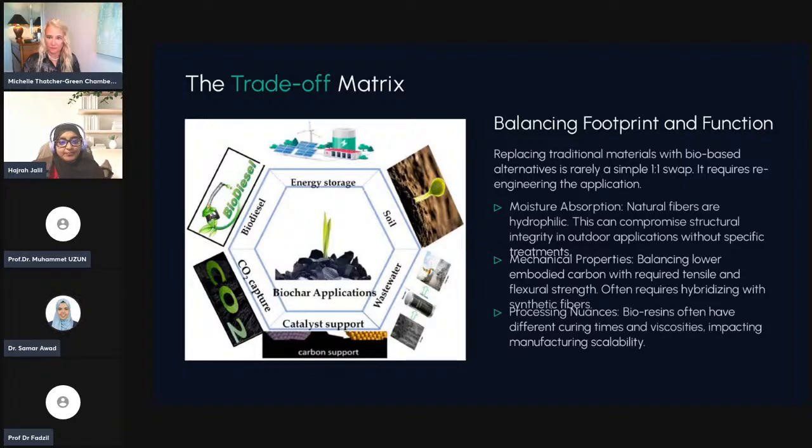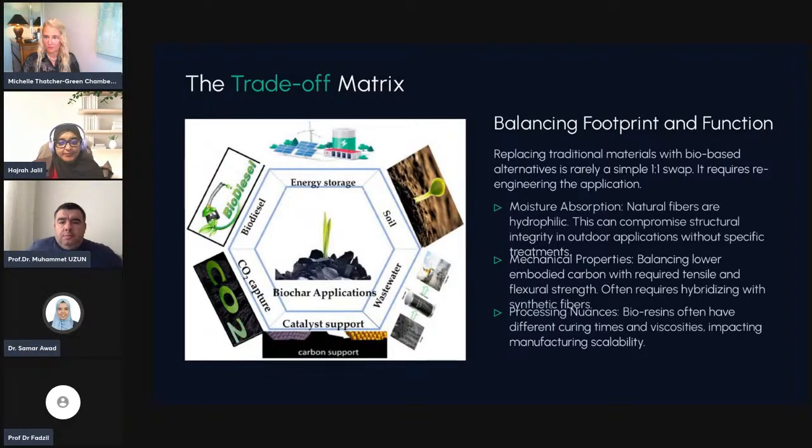Natural fibers are tricky. When we replace standard materials with natural materials, this process is tricky because natural fibers can absorb too much water or lack structural strength, meaning we must carefully mix and redesign them to function properly in the real world. So when we use natural fibers, we can make sure how they absorb water and measure the strength of these materials when we use them in a structure or as an envelope of a building. And I will present an experiment that will be published in an upcoming paper that I am testing with my team in the next slide. So next, please, Hagar.